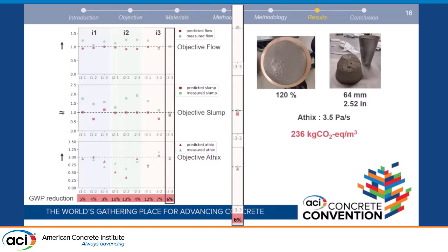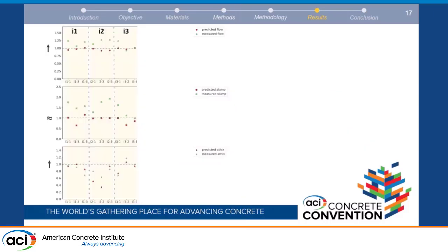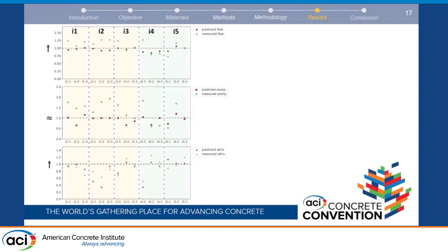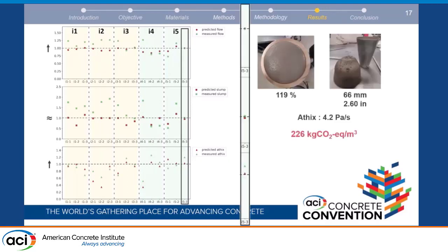So we can see that this is an effective way to reduce the global warming potential of complex materials, and we found a lower cement content mixture in as low as 9 additional mixes. And if we go one step further and expand the experimental region, so for an even lower cement content region, we can see that in 2 additional iterations, so 6 mixes, we find another printable mix with surprisingly good structuration rate, and with lower global warming potential.